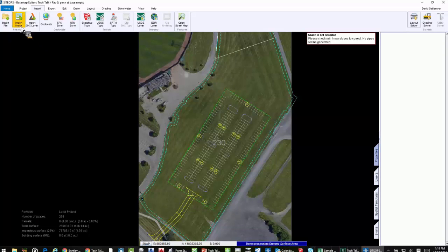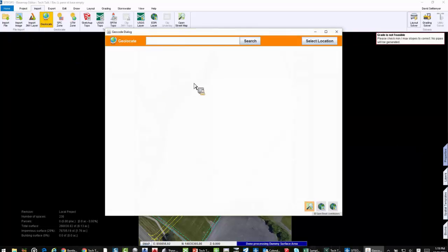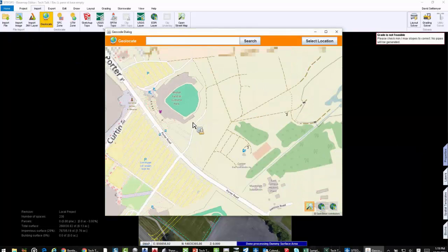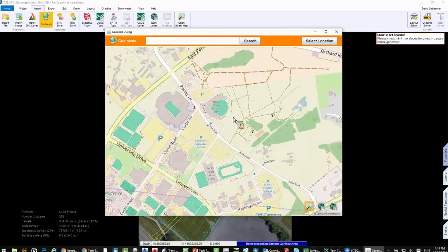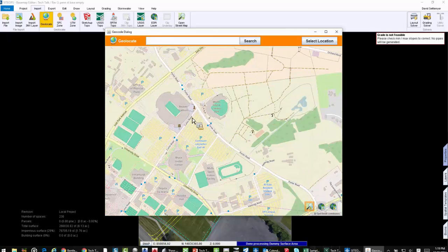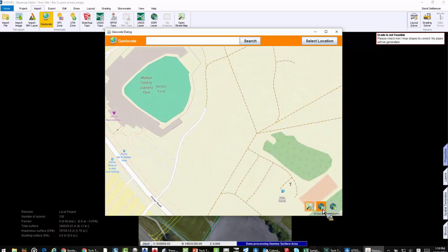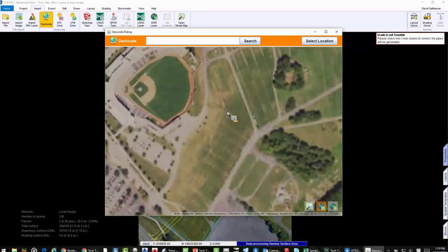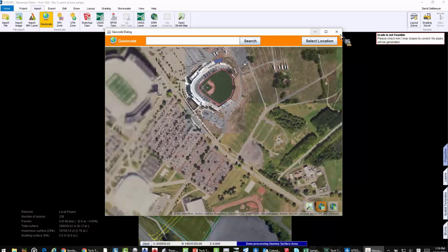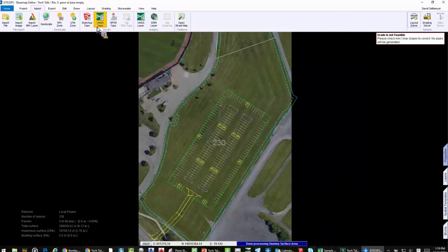A lot of our users really like to use this thing called Geolocate, which allows me to go in, and you can see right here it already knows exactly where I'm located. So if I wanted to locate this site, I could just put it in my view, say grab, and then from that point I can grab the USGS topography or the SRTM, and it creates a model and a surface for me automatically. Great question.